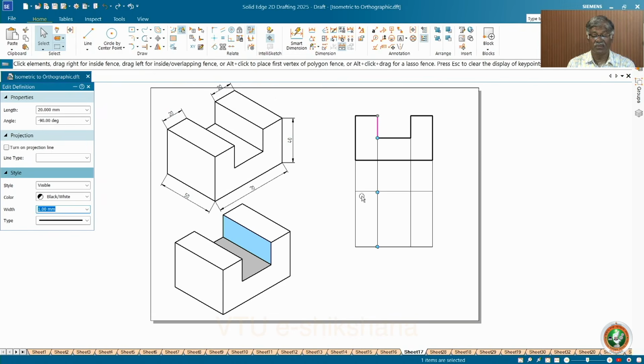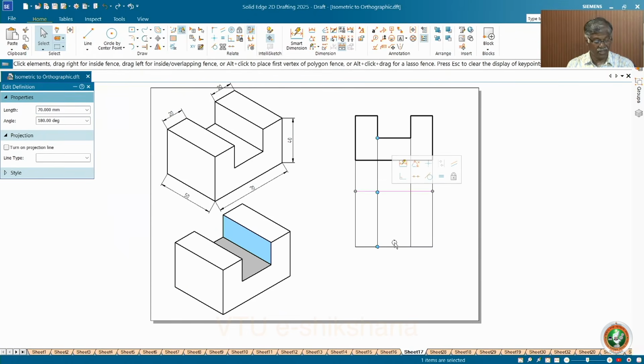Now, what about this? All these lines are dark because, even though it is a channel type, these edges are available and visible, as though at the top. Whether it is at the top or bottom, one and the same is visible. If you look from the top, this profile is a line. See, it's a line. Definitely there is a break, a corner is there. So you have to darken all these lines. Darken this line, darken this line, this. All edges are visible. Here there is some problem, I will tell you.